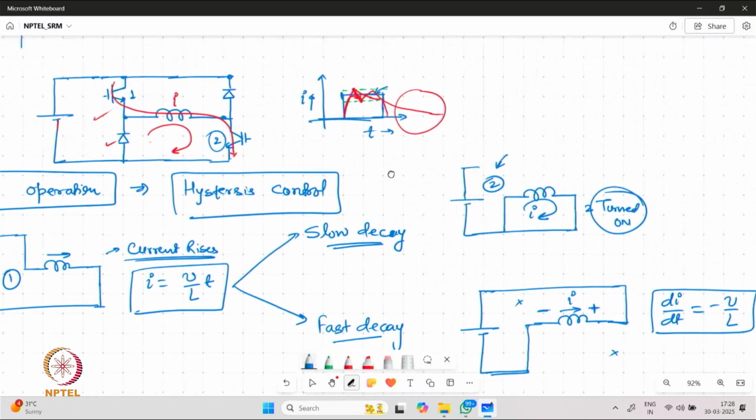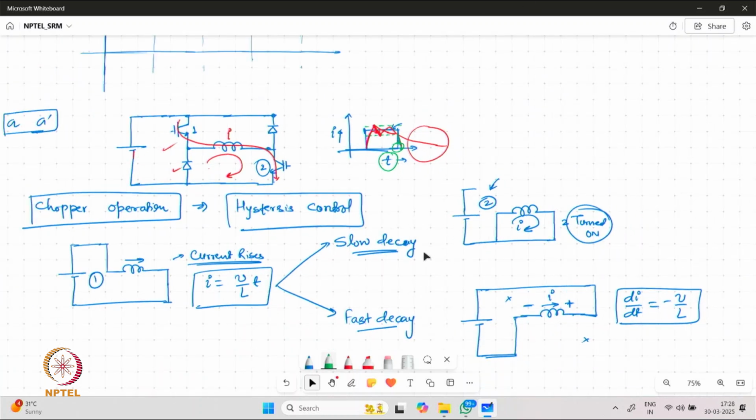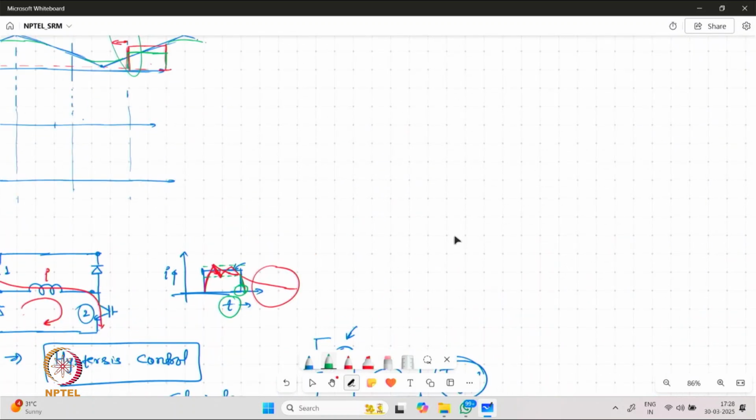This can be utilized for decaying the current in a quick fashion so that we are not violating the time boundary by a high margin. So in this manner, we can find that the current in the coil for each phase can be maintained on an average at the desired value by setting up some higher and lower limits and by following the hysteresis control.